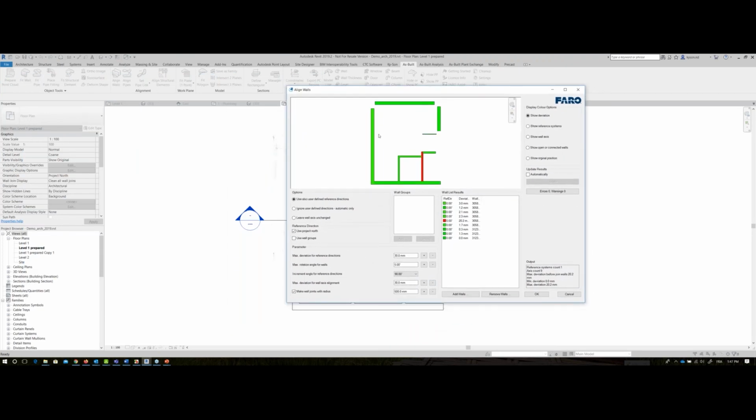So you see here, actually my walls are not closing and some here are not respecting my minimum tolerance here. By changing those parameters, I can ask the computer to close everything, and if it's below 5 degrees of angle here, it will adjust automatically for me.